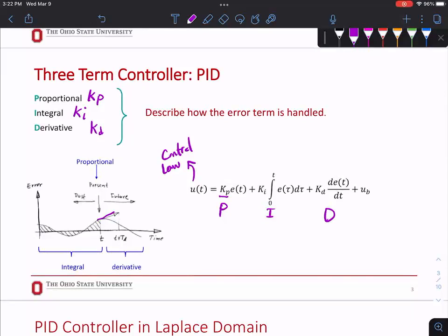Up to this point it is not difficult. Everybody can understand this. Now, what are those values? That's the problem, not the problem, that's the art. The art happens there, right? So when you're designing a PID controller, the tuning of it is what takes time. Now, PID controllers are usually tuned by trial and error. So zero scientific method. We can always come up with a good educated guess at the beginning, a couple of trial and error, and find a good value for KI, KP, KD. Once you have better intuition, your educated guesses will be better, closer to what the final value is.